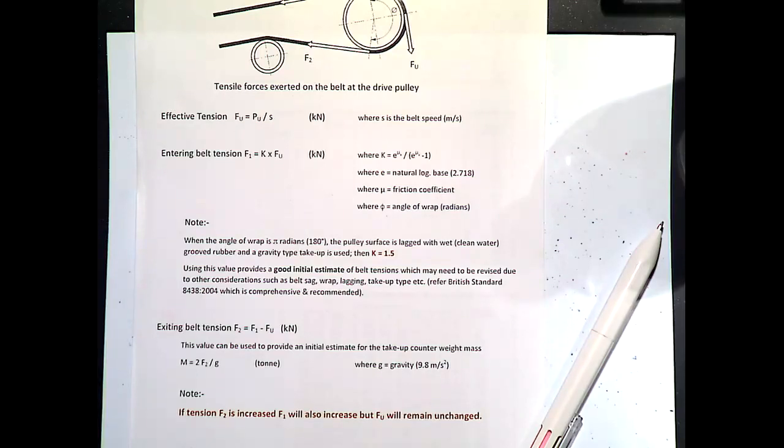Okay, but now the sag. They could have reduced the sag if they wanted to by putting the rollers closer together. Instead of having the idlers normally about 1.2 metres apart, they could put them in closer, but then you're doubling your cost. So it's probably easier to keep up the tension.